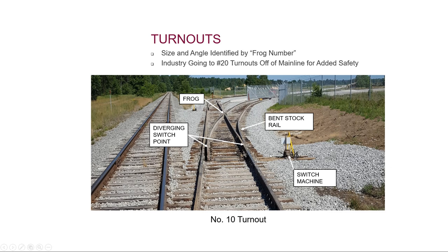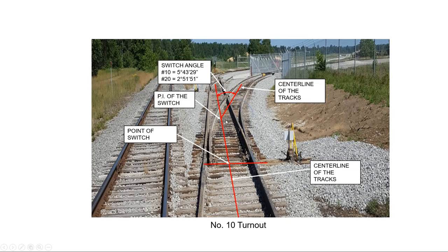This is bent rails. It's obviously curved through there. Here's the switch. All right, this switch moves this bar and that bar at the same time, and so when it slides over, the flange catches that, and then this doesn't catch this flange, and this wheel follows that rail around. And where this, I'd say, inside rail crosses what's the new outside rail, we call that a frog, point of frog over there. The odd term, I know. But apparently they thought if you looked at this from straight above, it looks like a squashed frog. That was the story I heard, why they call it that. That could be wrong.